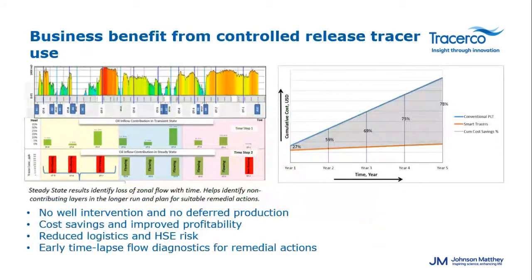Tying the flow rates from the transient production log to the geology, reservoir characteristics, and observations of decline of zones A1 and A3's production indicated in the steady state analysis allowed for completions changes to cope with the different reservoir properties, further enhancing production for this well and subsequent wells.